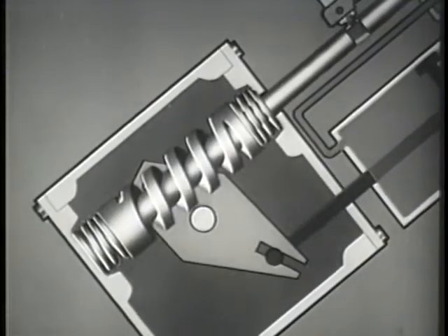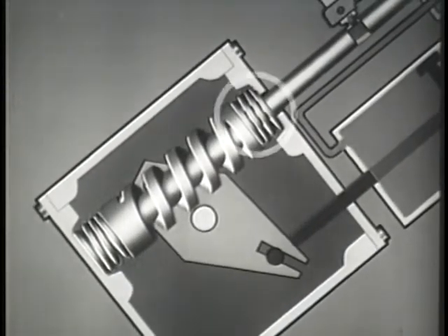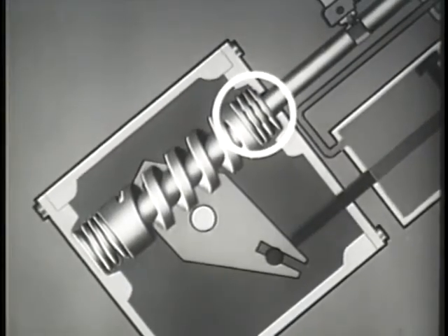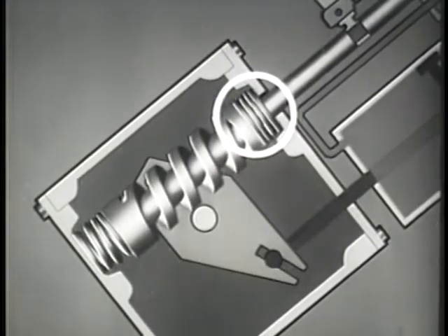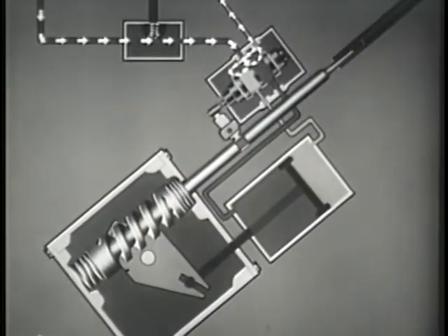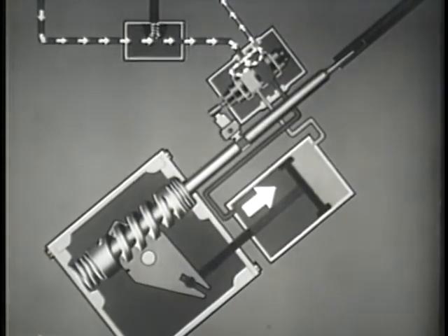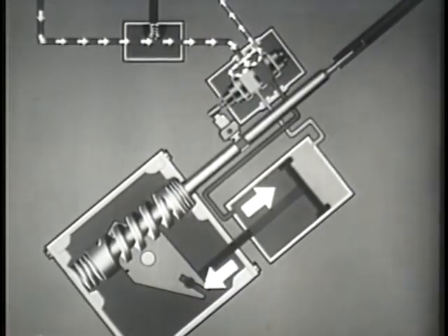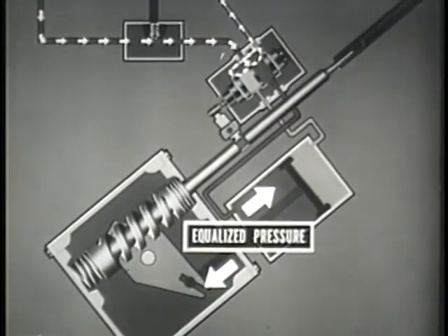These two opposing forces cause the steering cam to partially compress the upper cam spring. This also moves the control valve linkage and positions the valve spool where fluid pressure will equalize the force exerted by the steering geometry acting on the piston rod. The front wheels can then be held in any desired degree of turn.